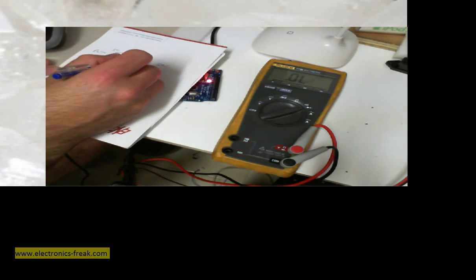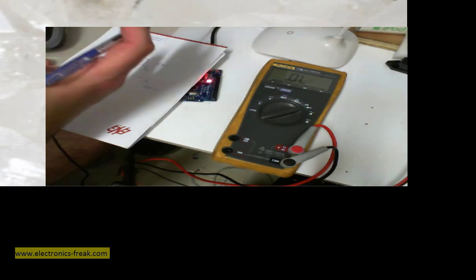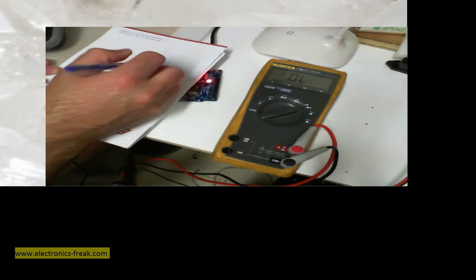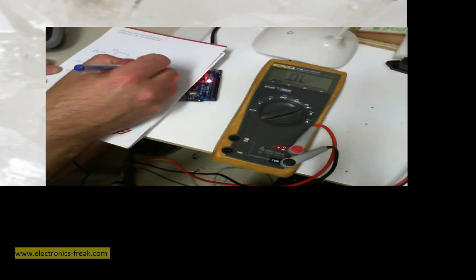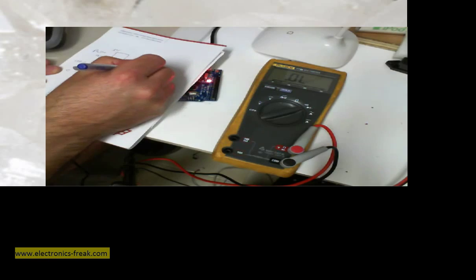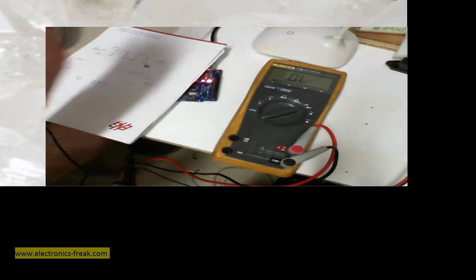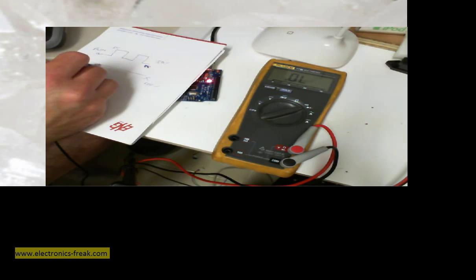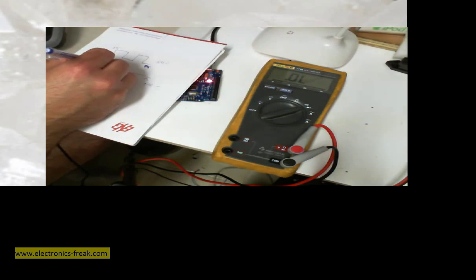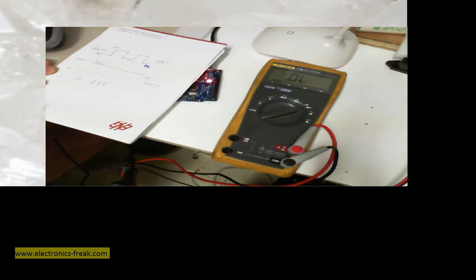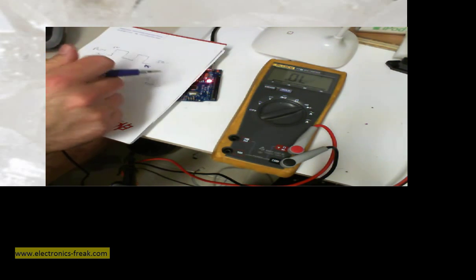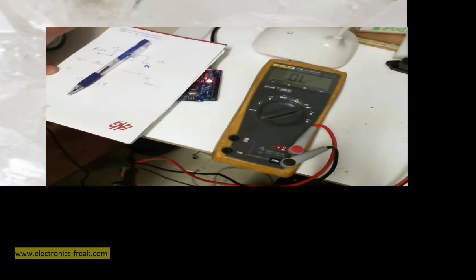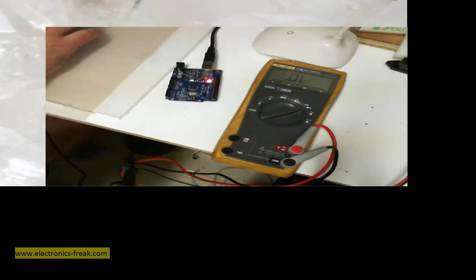So if this is a square wave, so the total value, let's say the average value, will be 50%. So in this case, the LED will light half of the power. If I will give a PWM of 100%, which is this one, it is always just 5 volt and not getting to 0 at any point of the time. So this is 100%, and in this case the LED will light the maximum light it can give out.